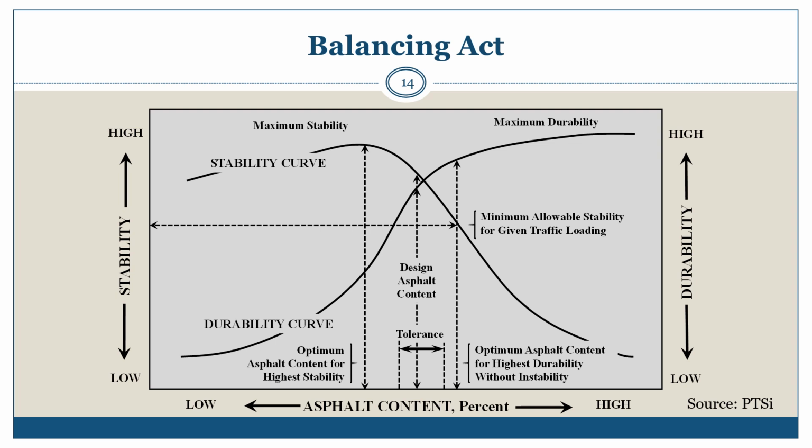Excess asphalt binder content may lead to stability issues or mixture susceptible to pavement deformation, whilst insufficient asphalt binder content may be the cause of durability issues such as premature pavement cracking.